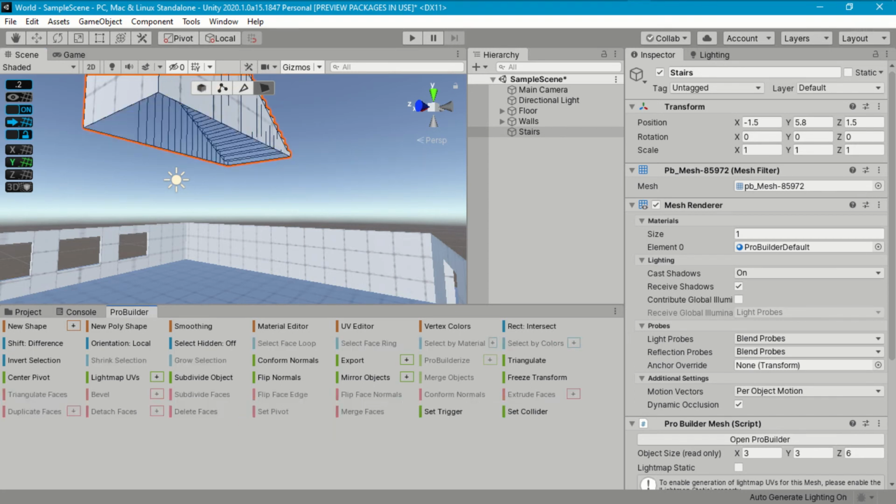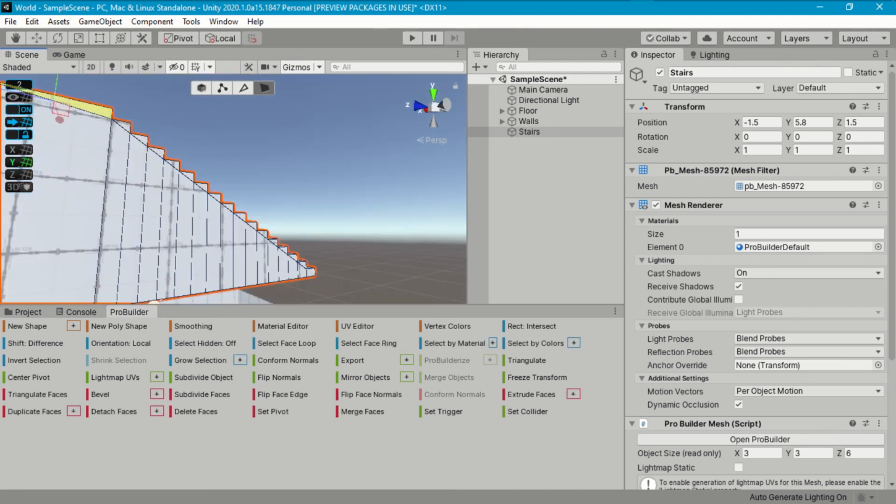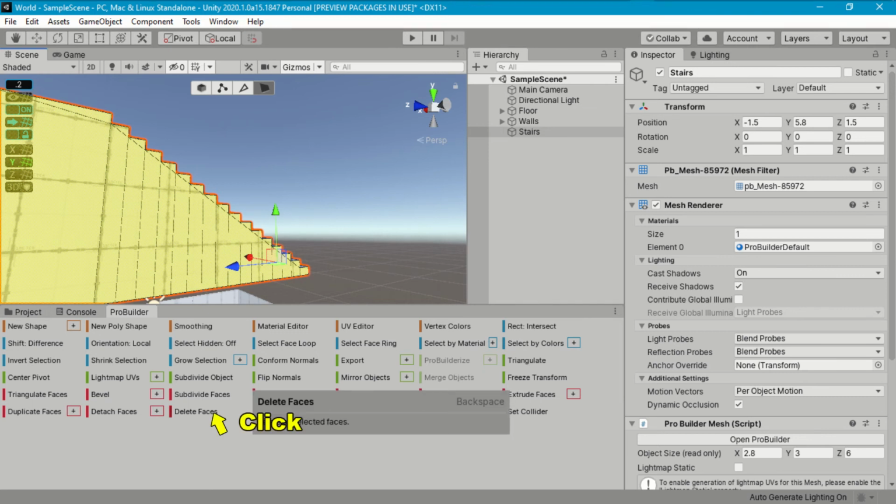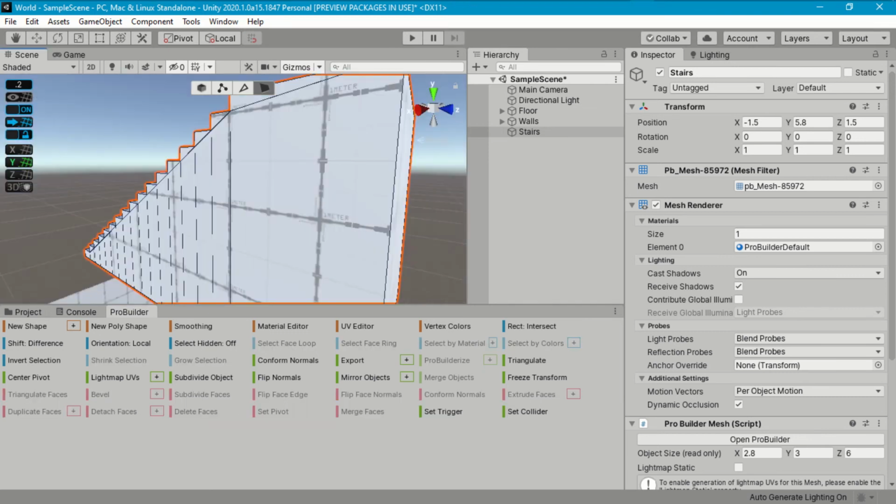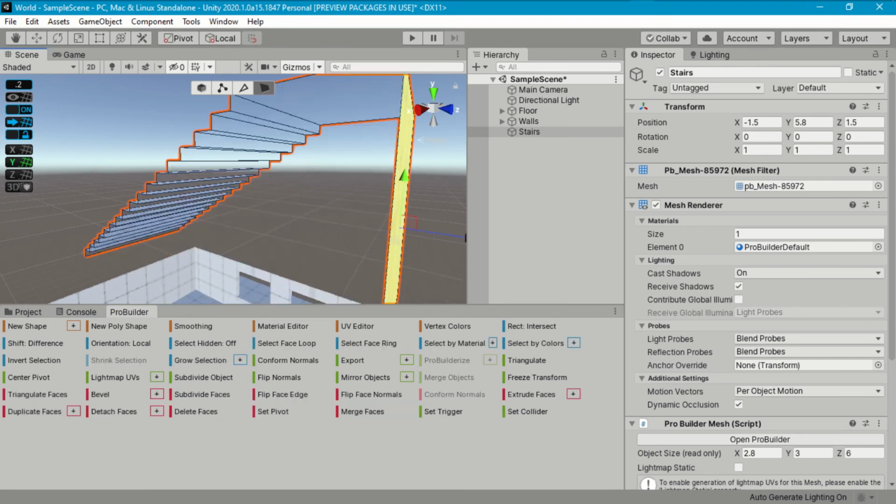We need to make room for a wall. That means we need to reduce the width 0.2 meters. So, please select all the faces on one of the sides. Then push them inwards until they snap, and delete them. Orbit around to see the opposite side. Select all the faces, and delete them. Also delete the back face.